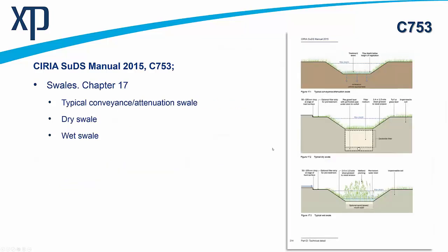There are different types of swale. The one that you just saw the photograph of is the top one, which is a grassy lined swale. This could be used purely to convey the water for that 150 millimeter vegetative zone for the regular events, but then also to provide storage for the more extreme events. And then we can contain volume within the swale. They're very, very good at this.